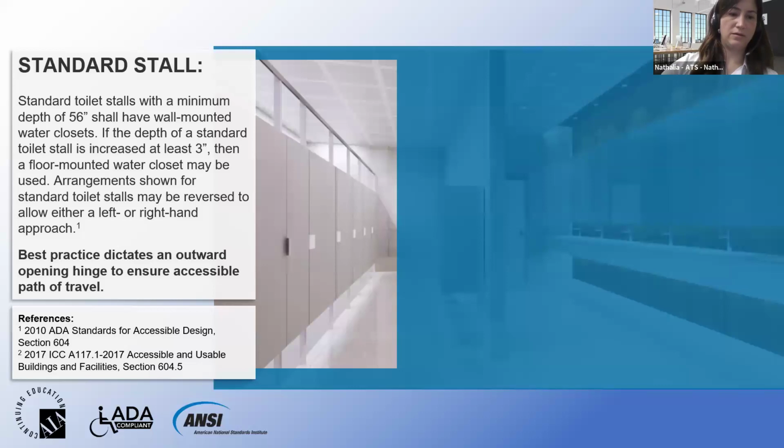Some arrangements shown for standard toilet stalls may be reversed to allow either a left or right-hand approach. The best practice dictates an outward opening hinged door, of course, to ensure an accessible path of travel. So always for the accessible stall, make sure to use an outward door.